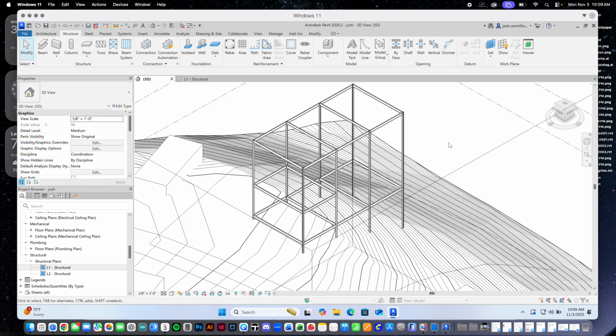But this is just, again, a refresh of the things that we were doing before. Anyway, we're just adding more beams now. And I found it much simpler to go to the L1 structural plans, the framing plans, L2 structural and framing plan, so that it's a lot easier to draw those in that plan. You can see the beams as you draw them as single thick lines, on the center lines basically, right?